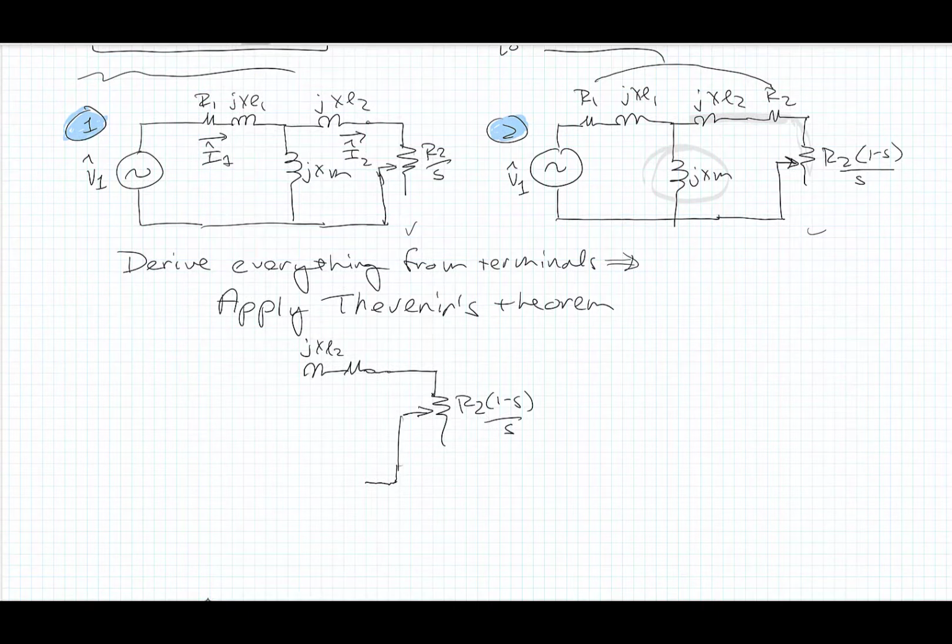I can do that by creating a Thevenin equivalent circuit, where I have a Thevenin equivalent reactance for the stator impedance called jXL1 equivalent.